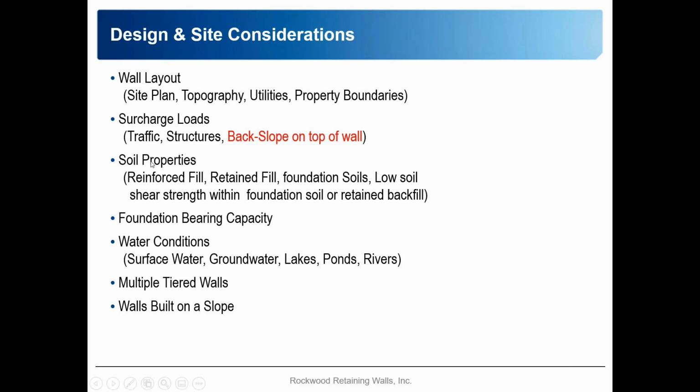Another thing that's important from an engineering or design consideration standpoint is what type of soils are on site. Rather than get way deep into it, I can just sum it up: sandier materials, granular, more free draining soils are good, and clay soils that have high silt content, that are more prone to water absorption or changing their properties when moisture is added, are bad.